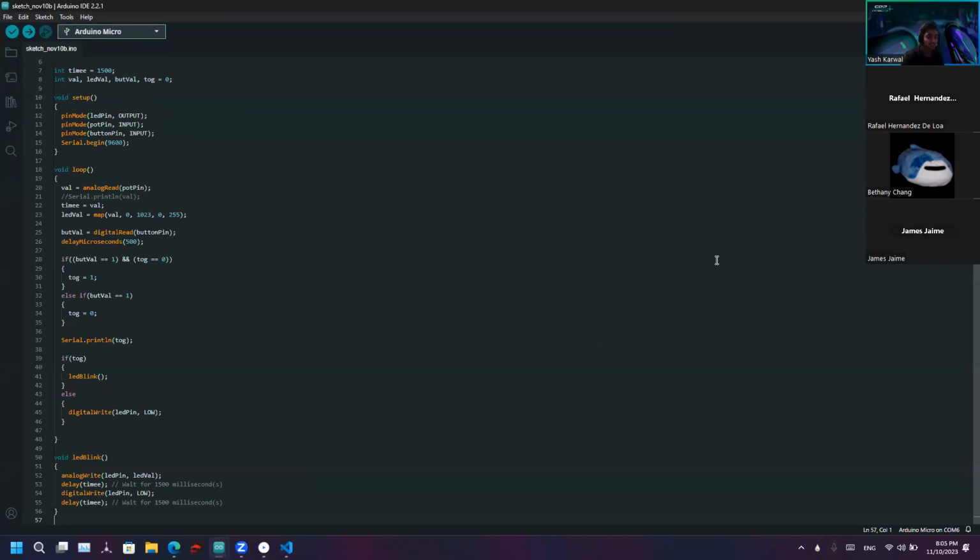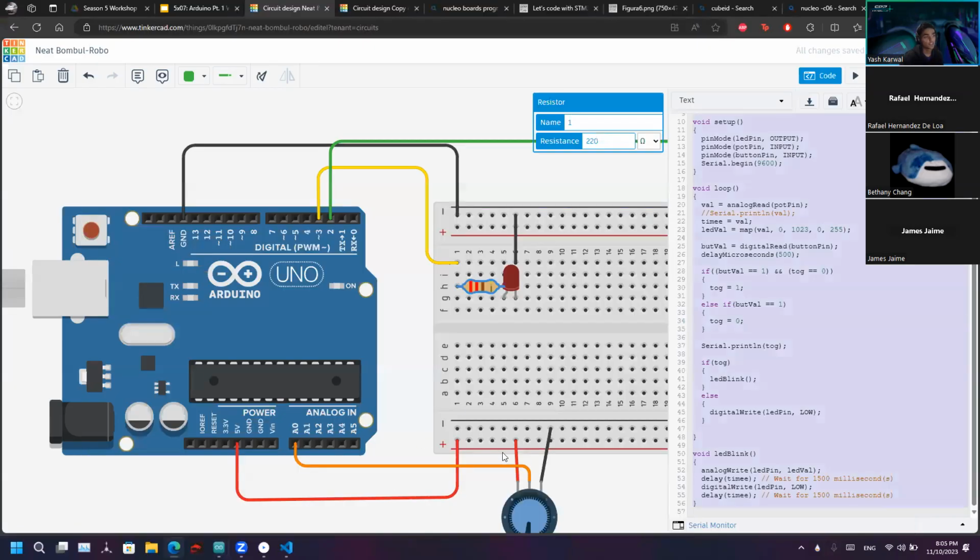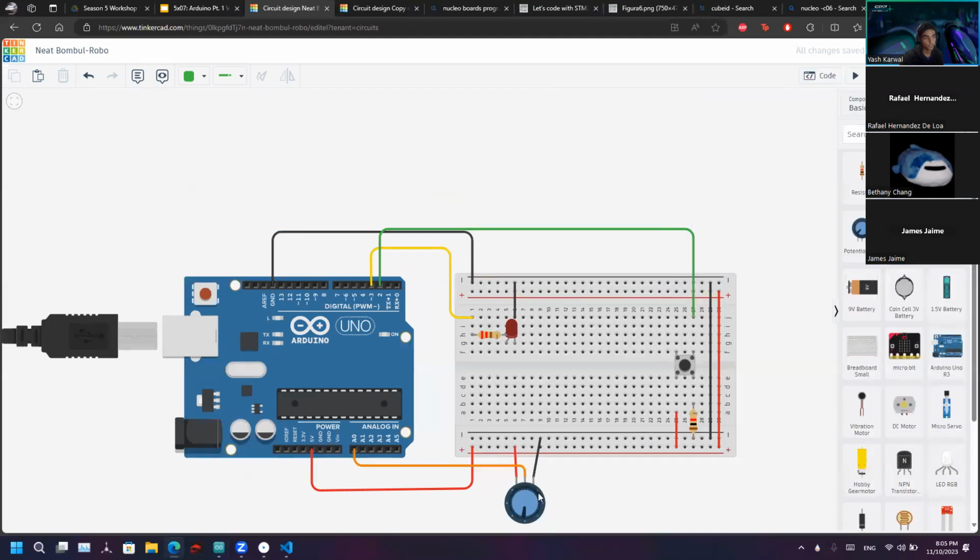Oh yeah, that's right. In its current state, you have to put the potentiometer at a lower value, because we put the delay also with the potentiometer. So we need to lessen the delay so that it can catch when we press the button. Just twist your potentiometer to a lower value and then try pressing the button again. It probably does work. It's just that the current delays in the code are causing it not to read it whenever you press the button.